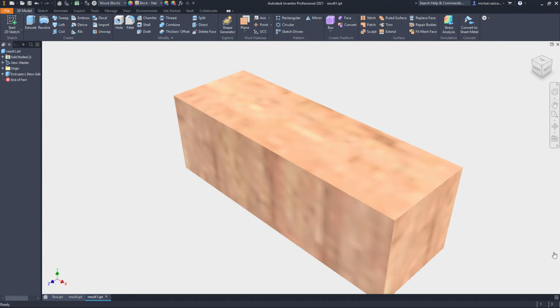That's all cool. Big advantage of this solution is that even though you are not specifying link to iLogic script every time when running work item, you can still change content of the script before running any work item. Simply because work item downloads the content right before processing command line.